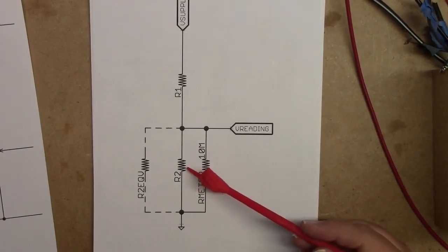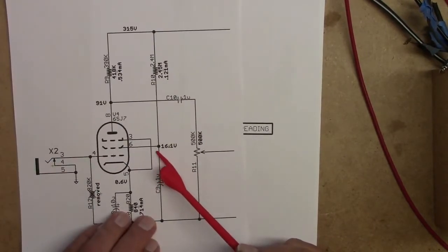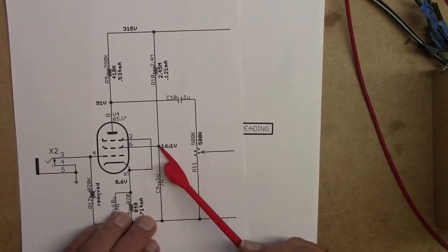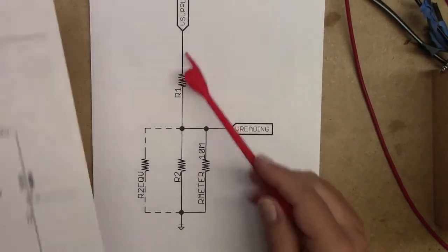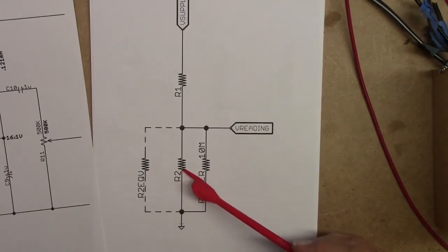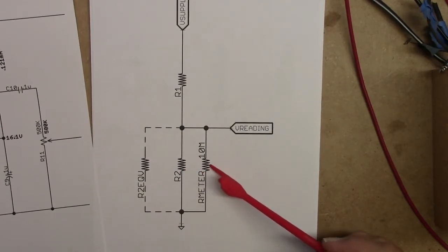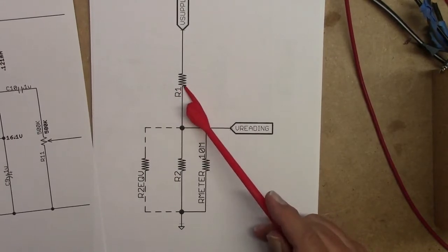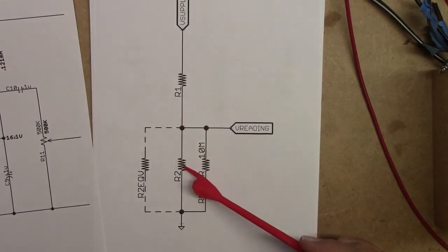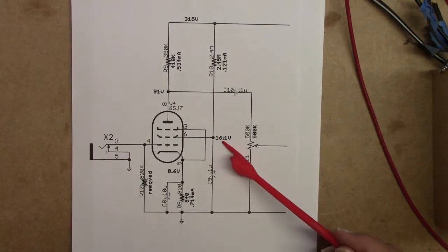And then if you take a reading on the real circuit with your meter, and then you use all those four numbers, this one, this one, this one, and this one, you can calculate what R2 is. All right. Then from there, what you can do is effectively take this out of the circuit theoretically, and now you're left with the screen resistor and the screen impedance, and you can determine this reading a little bit more accurately. So what I measured, I didn't actually measure 16.1.